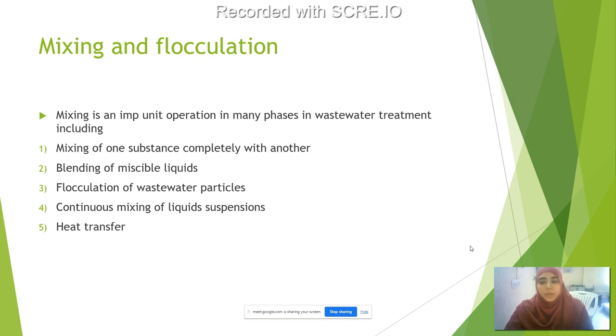Mixing is an important unit operation in many phases in wastewater treatment, which includes mixing of one substance completely with another, blending of miscible liquids, flocculation of wastewater particles, continuous mixing of liquid suspensions, and heat transfer.